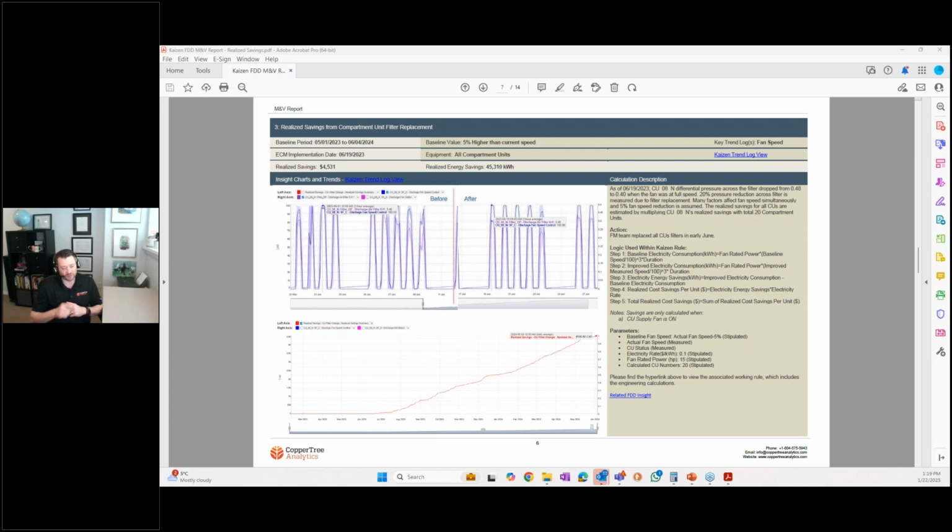But we would check that before we go ahead with any tests, and that's something that we do regularly with the ACX application. For instance, making sure that the interlock between the systems is functioning as we expect. And there's always safety, fire damper control, et cetera, that's going to override. Again, I think we're writing at priority 16 on BACnet, if I'm not mistaken. Don't quote me on that, but it's a very low priority that we're doing. So anything that would be built into the BAS as a safety would take precedence.